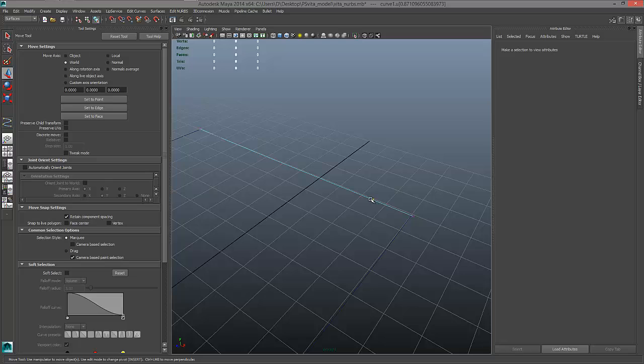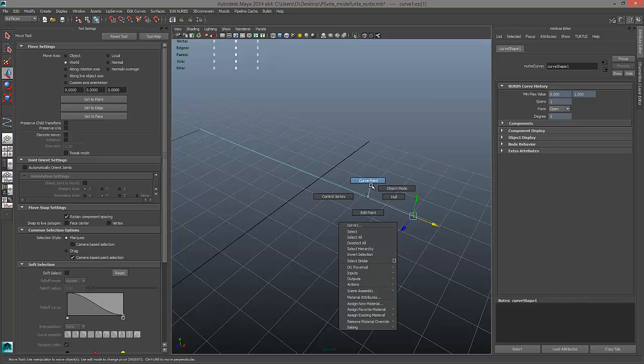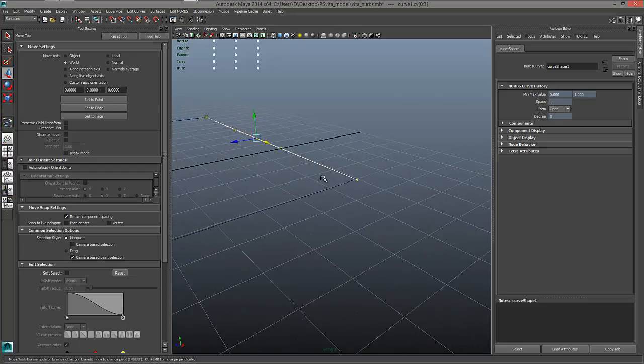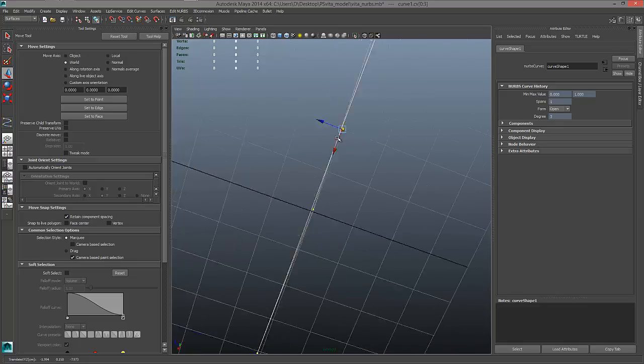And then I have my edit point, which is kind of the same thing, where I get to click on the edit points of this and move them. And my last one in here is hull. You can see when I'm in hull mode, a hull is basically a complete line, so I can move that whole entire line in hull mode.